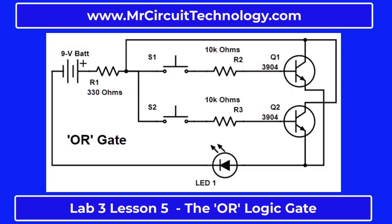In this OR digital logic gate circuit, the engineer designed it so that the LED will light up when you forward bias either one or both of the transistors. When you press switch S1, the current will flow from the negative of the battery through the LED and then through transistor Q1 through resistor R1 to the positive of the battery.